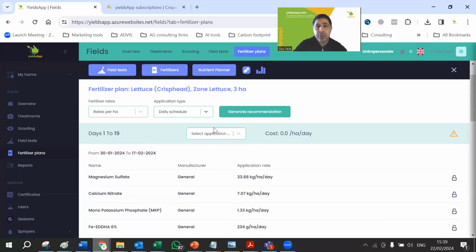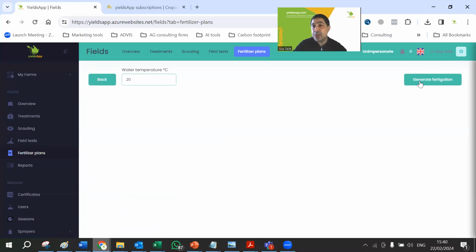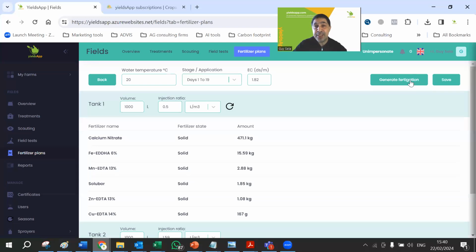I want daily schedule, and I want a proportional fertigation, right? So I do that. First, it gives me the rates of fertilizers per hectare per day in this case, and then I click on fertigation. All I need to do here is to click on generate a fertigation, and look what happened just here.